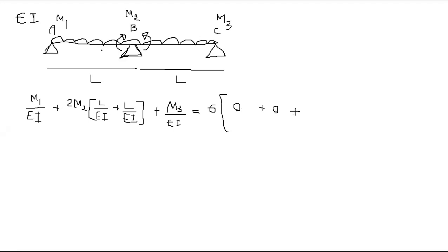So you need to consider the simply supported bending moment diagram. For each case, that will be similar, because both have a similar uniformly distributed load. That will give you a bending moment diagram like this, with a maximum of WL squared over 8.